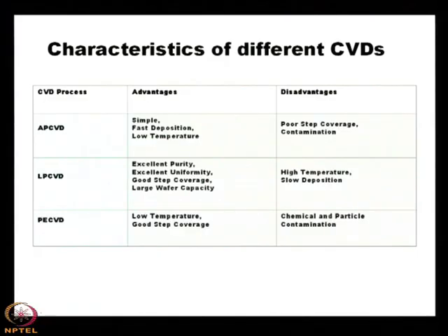Layer 1 metallization must be covered by some insulation layer before making layer 2. Then again before making layer 3, you have to use some dielectric layers between the successive metallizations. All those things are done by these processes, CVD or LPCVD or physical vapor deposition, whatever be the technique.